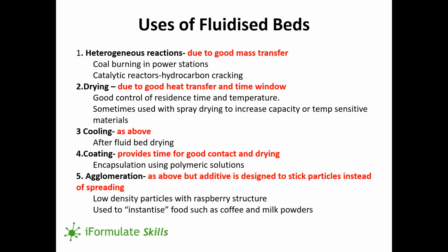Often what comes out of a fluidized bed is hot material that can have flow problems themselves if they're allowed to settle, and so often you'll have a fluidized bed dryer followed by a fluidized bed cooler, and I've used these many times with agglomeration, particularly for detergent particles. So we'd have a fluidized bed dryer, and then we'd follow that with a cooler, where instead of pumping hot air in, we pump cold air in in order to cool the particles. And again, they're very efficient, and it's used then to give a nice, crisp, free-flowing product.